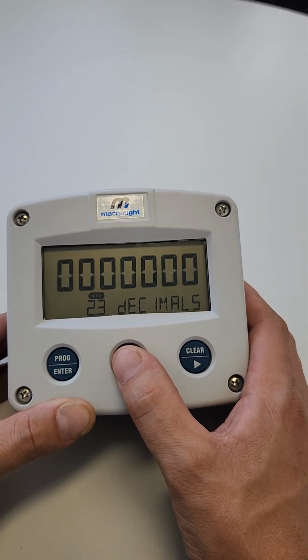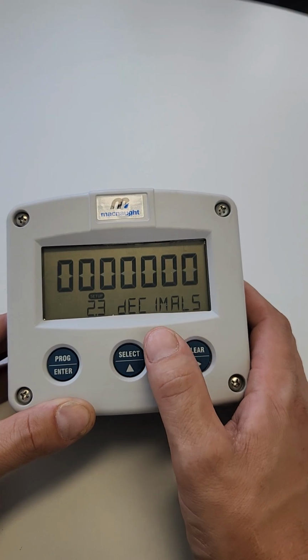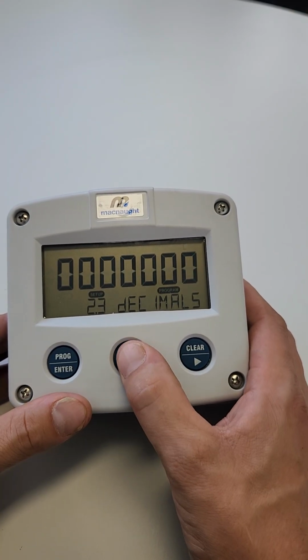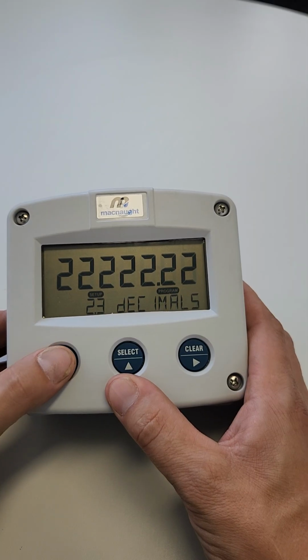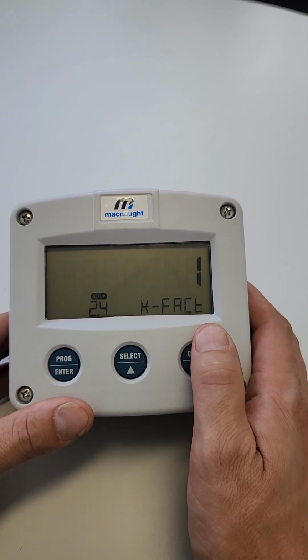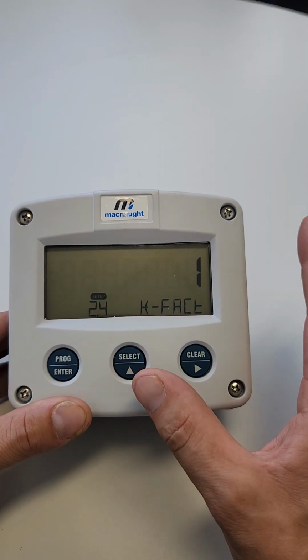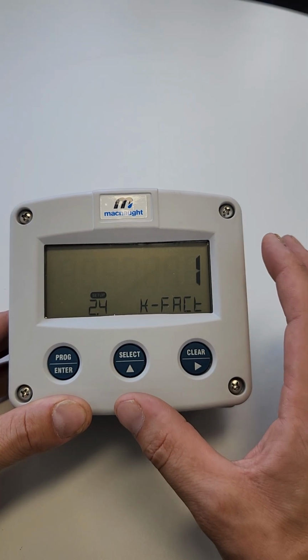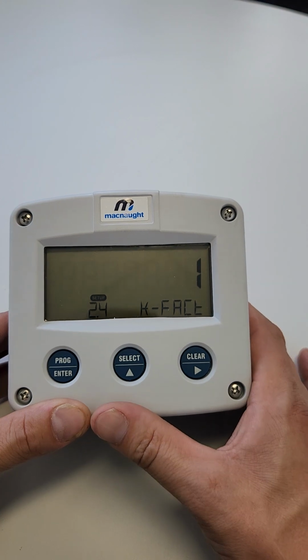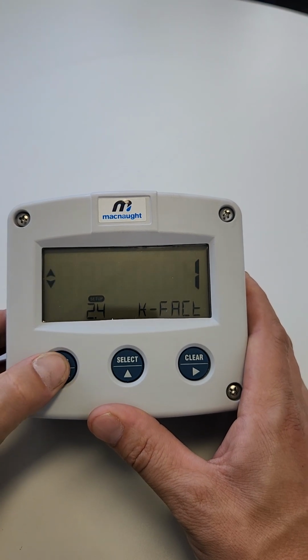2.2 we don't need to change, default settings are correct. Decimal places, we want to change that to 2 as well. So we hit program, change that to 2, lock it into place. Number 3, the K factor again. The K factors need to be entered into the total and the flow rate section, so there are multiple spots where it needs to be put in. So if we want to change this,